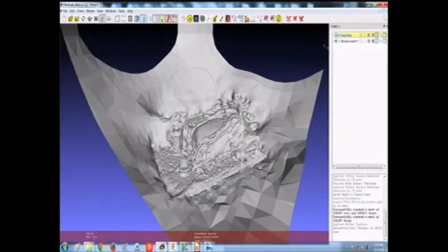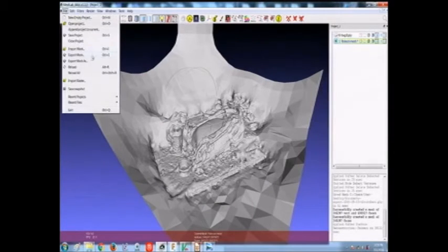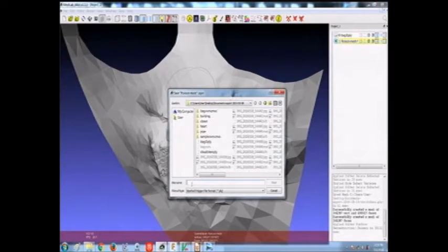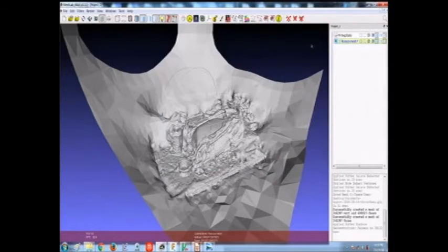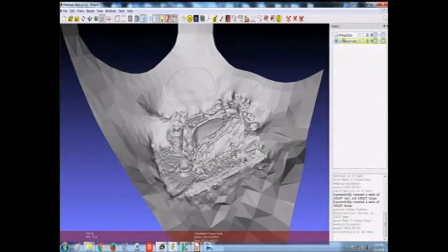Okay, so let me save this Poisson mesh. Remember what I said, save early and save often. Export this mesh as a Poisson. And Meshlab is very, very picky about which mesh you have active. The active mesh is the highlighted one. And there's also a mesh dialog box here, the layer dialog box, which gets you into that submenu.